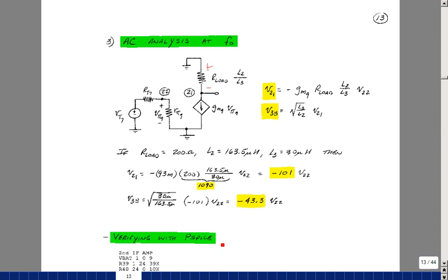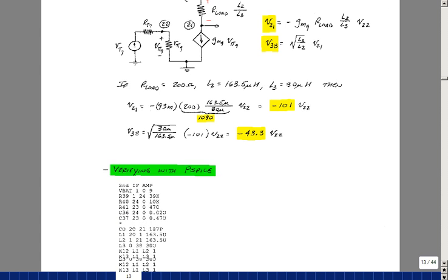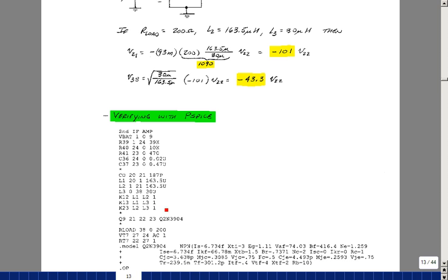Let's see how close we come if we were to simulate this in SPICE. Again, using an ideal transformer with the coupling coefficients of 1. And these are the values of the inductance I roughly measured from the transformer, and also the capacitance across the input terminals.